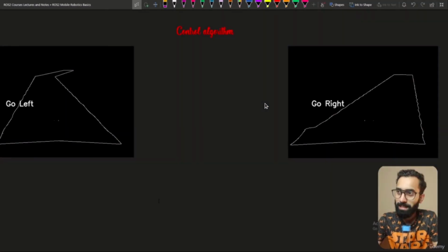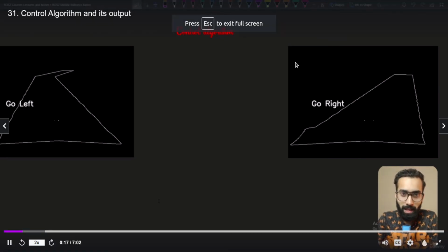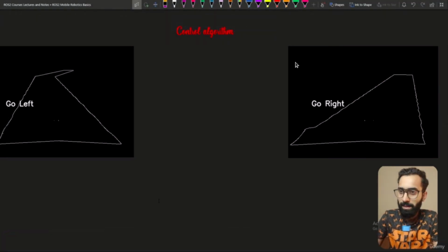Coming to the last part of this line following algorithm building project of Prius hybrid, the control algorithm is going to control the car and force it to go back to the center of the line. Now we have this small dot as the center of the line. The second point, which is a little bit darker because we added adjacent pixels value to be 1, is the frame midpoint and line midpoint. What we did is apply the proportional controller.